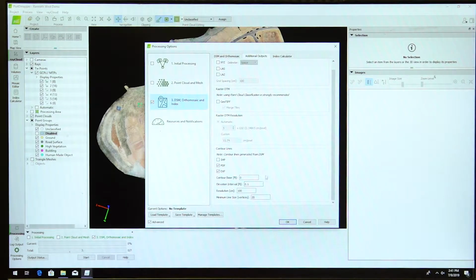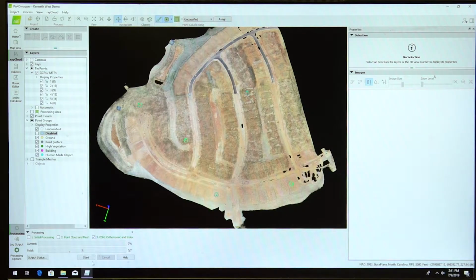Due to the fact that if I'm building a surface off my contour file, I get a more accurate surface at 1/10 of a foot. I get more contour lines to build that surface off of to compare to a design surface or a month previous flight surface to get up-to-date cut fill maps and to see how the job's progressing. You just hit OK here, click step 3, hit start.